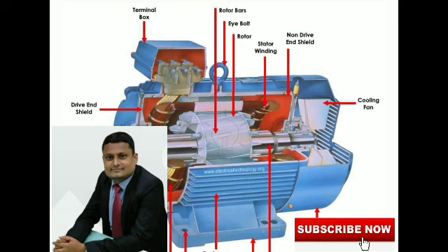So once again, the choice of current density: the advantage of a high value of delta S is reduced conductor cross section, cost and weight. The disadvantages are that resistance increases, copper loss increases, temperature rise increases and efficiency will finally reduce. Usual range is 3 to 5 ampere per mm square, and higher for smaller machines.